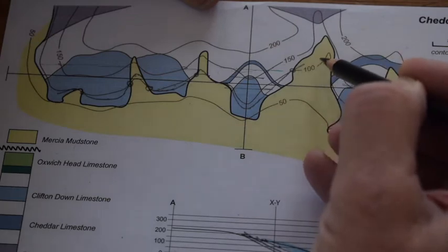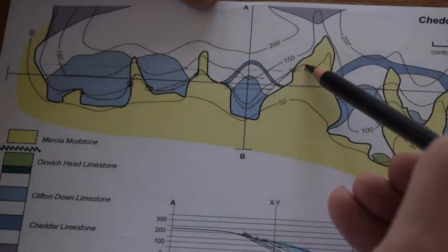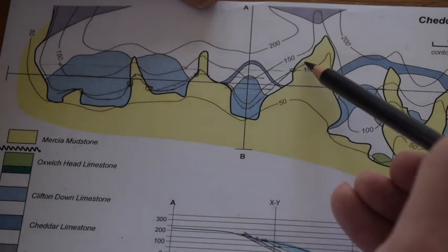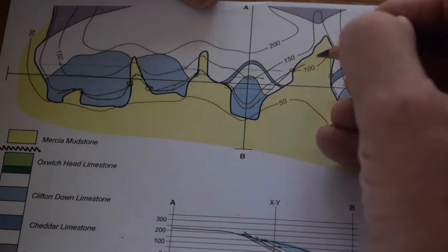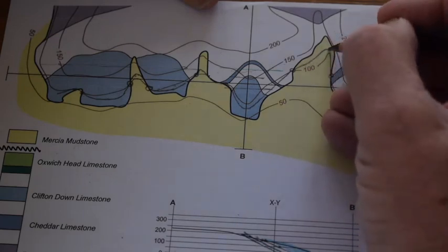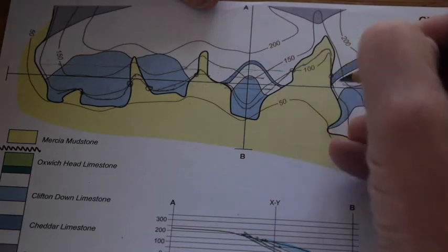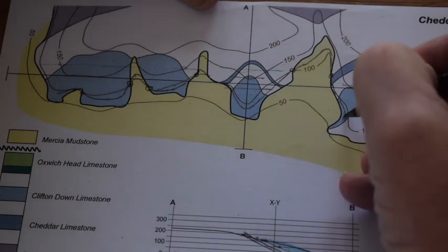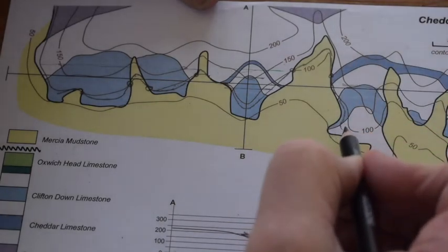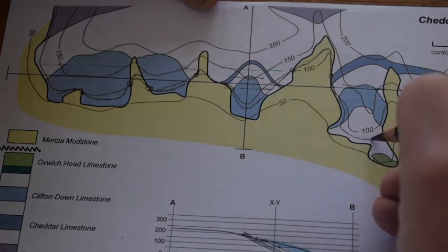beneath the Trias, so that the value of the topography is somewhere between 100 and 150. The structure contour is 100, so it's in the subsurface, has a lower value. It's going to emerge back out there, so it has to swing all the way around here, tight around that, and back out, and really tight to the boundary in here, because there's the 100 metre topographic contour quite close by. Something like that. Could come a long way out around here. We don't quite know where it is in here, and then out.